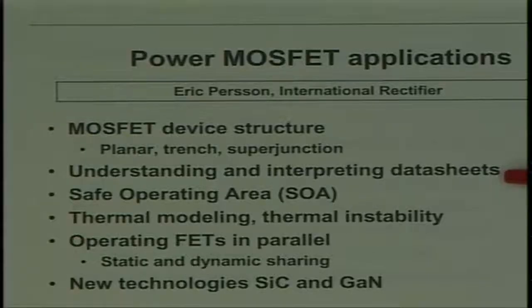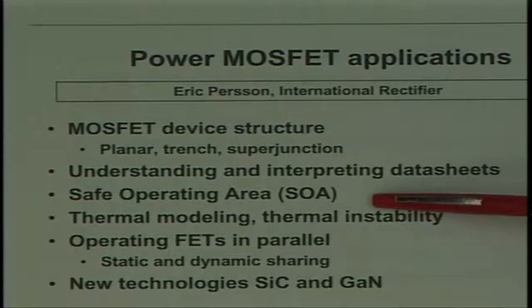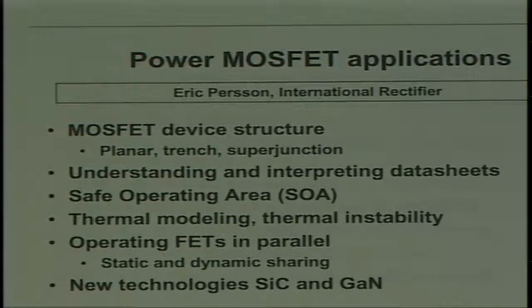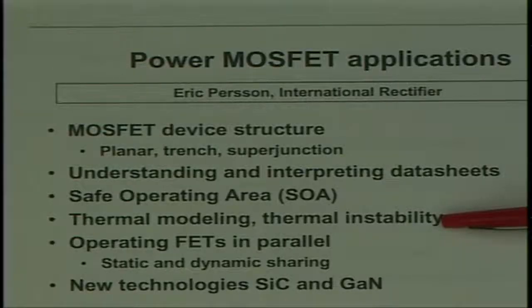Another big one is understanding and interpreting data sheets, which can be sometimes very confusing or misleading. And included in that is safe operating area, what that means and how to use it. A little bit about thermal modeling, because usually the limits of a device are not actually what it says on the data sheet, but rather how hot it gets and how you can manage that in your design. A little bit about thermal instability, which is a fairly new phenomenon as devices become more and more dense.